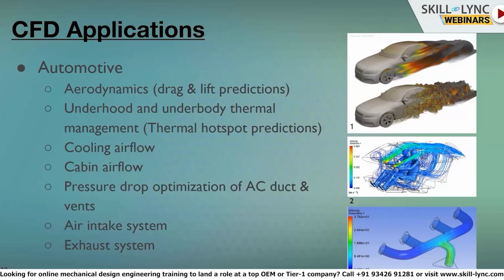So all those things he has to take care of. The CFD engineer who is working on the cabin airflow: obviously this air comes through a duct and is blown by a blower, so he has to optimize the pressure drop in the duct so that he can improve his blower performance. Then obviously there is a vent through which the air expands into the cabin.